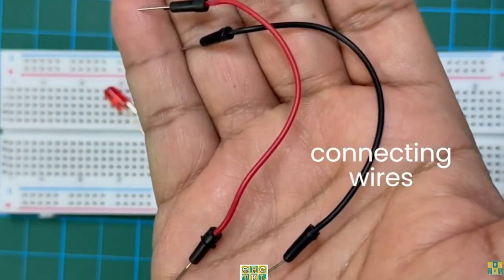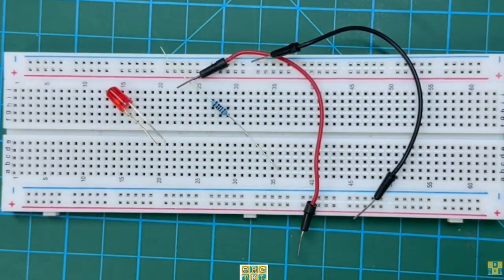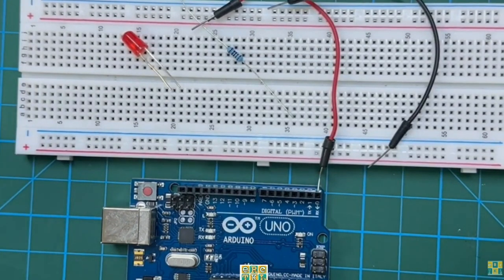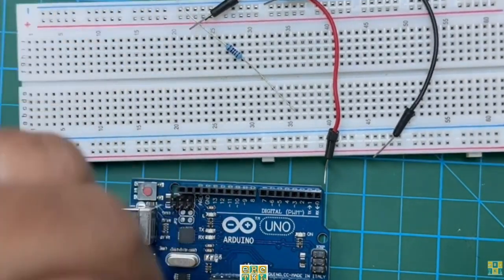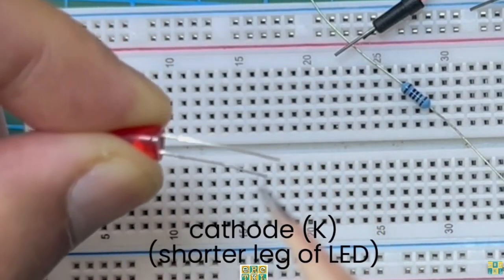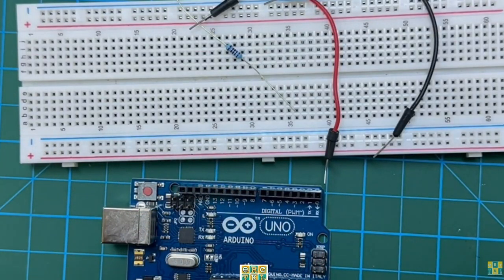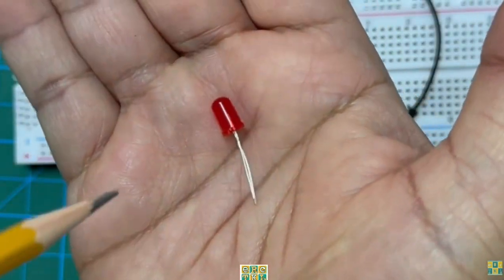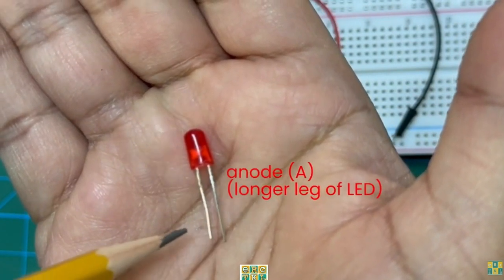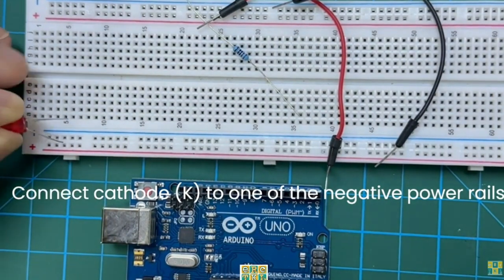And we need connecting wires to connect our circuit. And we will be using red and black connecting wire. Now, what we will do now is we will connect the cathode, the shorter leg of the LED, to our breadboard. We can choose any point, but for this example, you will see later on where I will connect it. But then the longer leg of the LED, that's called anode. Okay, so for those who are doing 105 now, I think you are done with diodes, so you know this.